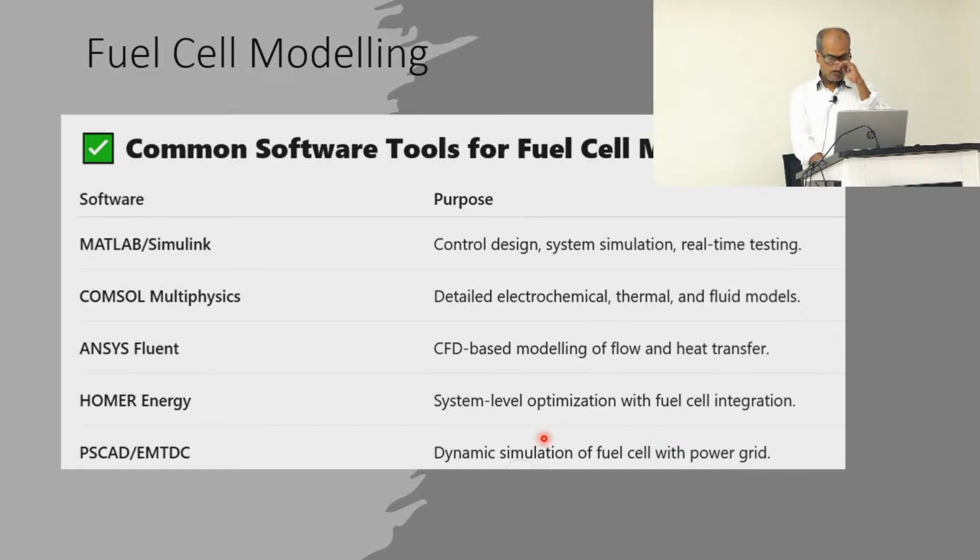And if you want to do network-level simulation, either electromechanical or even electromagnetic, for electromagnetic, probably PSCAD is the best option. PSSE you can use for electromechanical, where it doesn't involve the dynamics from power electronics. But if you want to capture the power electronics, then I think PSCAD is the best solution.